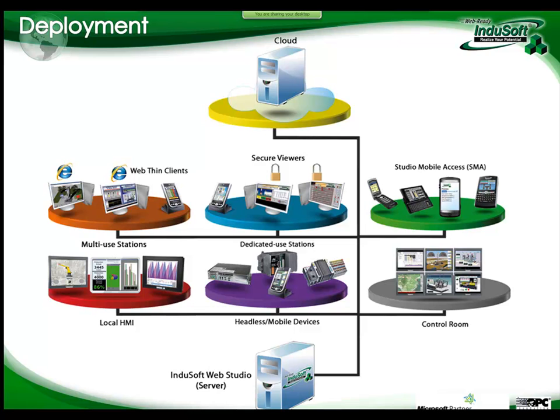So on this slide here, we're gonna show the different options you have to present that data out. Starting on this level down here, you could be running InduSoft Web Studio on a server computer, so that would be your bigger application talking to all the IOs. But you could also be running InduSoft Web Studio as a local HMI, let's say a PC panel, or one of these types of headless devices.